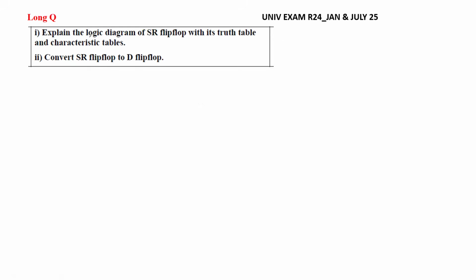First, they are asking to explain the logic diagram of the SR flip-flop. You know that this can be designed with the help of universal gates. Either you can use NAND gates or NOR gates. We design it with NAND gates.